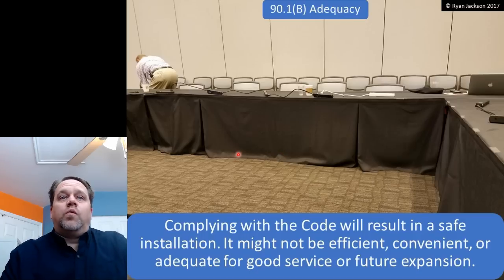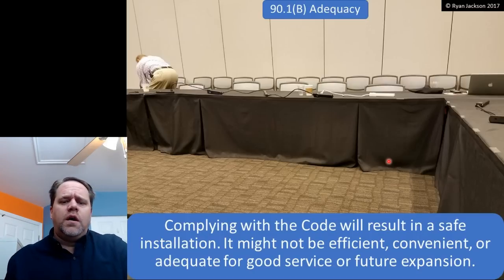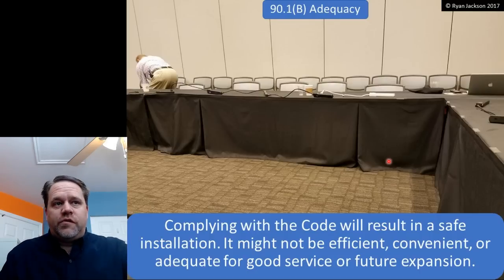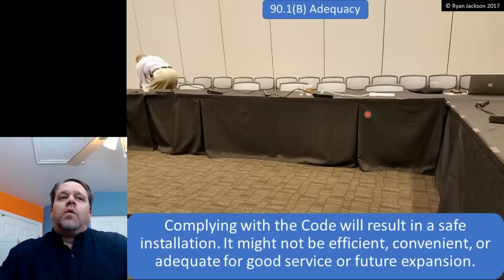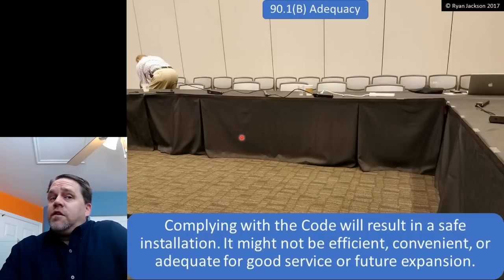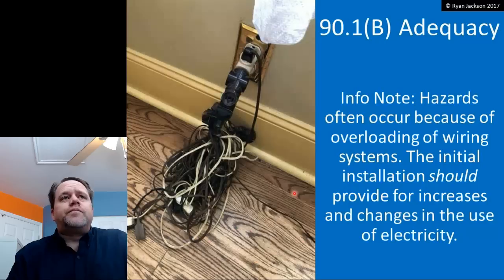So in a perfect world, we would have had more receptacles throughout this meeting room. And in fact, in the 2017 code, in section 210.71, there might even be requirements for more receptacles in a meeting room. But those rules weren't in place at the time this picture was taken, or when the building was installed. So this was okay. But the bottom line is this was, in fact, safe. Might not be efficient, convenient, adequate, but it's going to be safe if you follow the code.